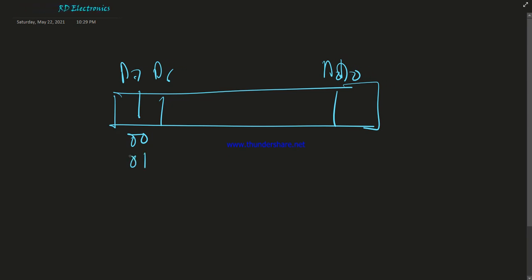If 01, then stop counting if the timer is running, otherwise no effect on the timer. When 10, then stop after terminal count, that is, stop at the end of the count if the timer is running, otherwise no effect on the timer. And if 11, then start the timer if it is not running.